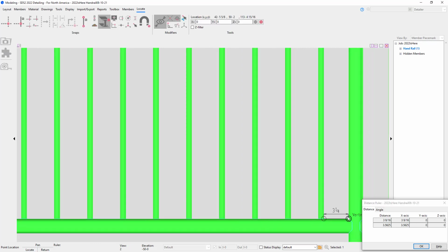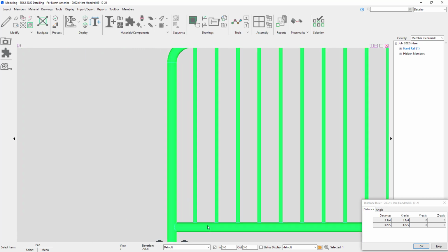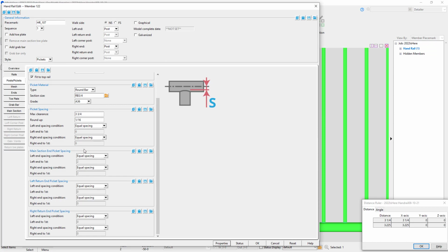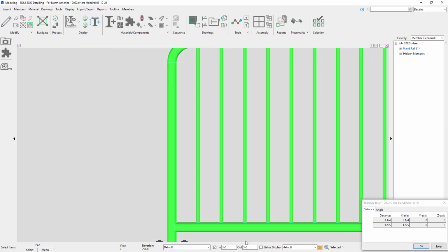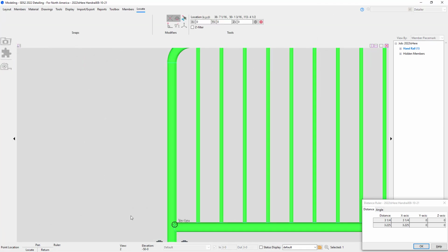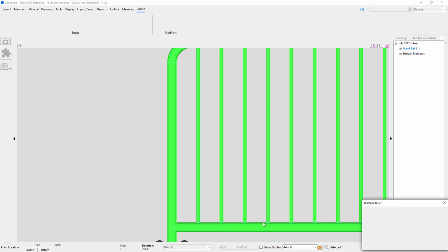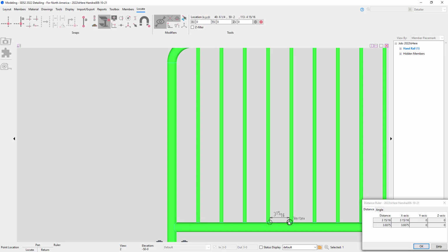As you can see, we split the first and the last dimension to make this all as close as possible and have the face-to-face add up. Boosting the maximum spacing to 4 inch will now give us even better results for equal spacing, and we'll have everything add up exactly. We found out that you can get less pickets in most cases and maximize the spacing.